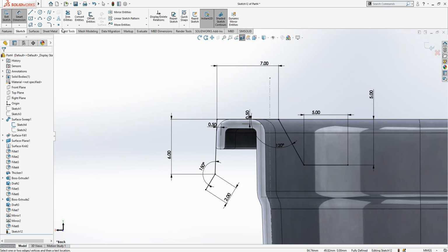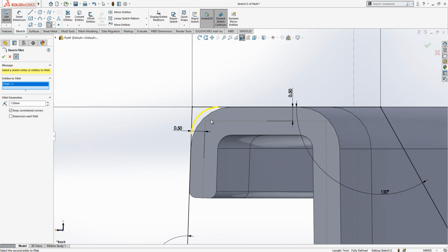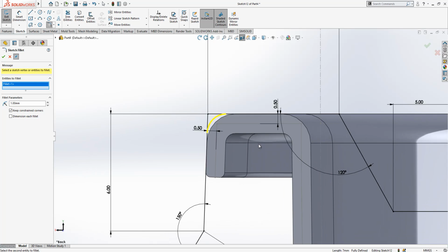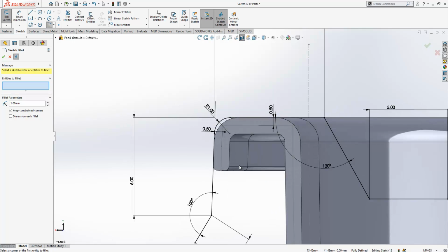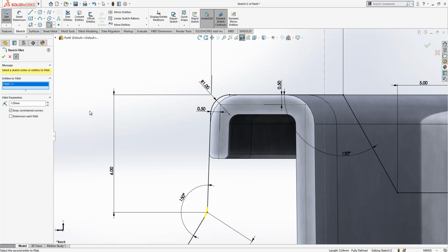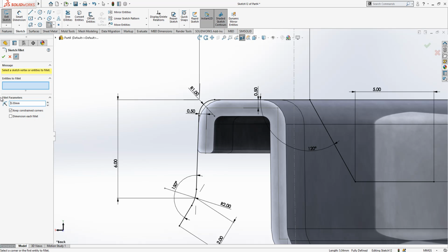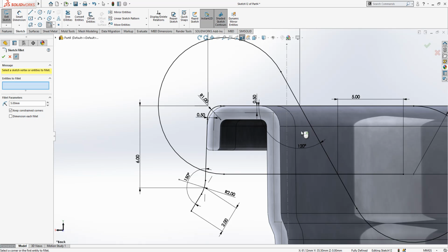I think I'm going to give my radius values now. 1, let's try 1 here. We shouldn't make everything overlapping because this is plastic. No radiuses, no values will be the same. Then you will have a problem when you are closing your parts. Even normally, in reality, I would give some gap here as well, but this is for the repetition's sake. This is an example and tutorial. I will not bother myself with so much detail.